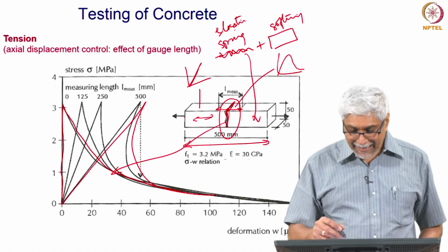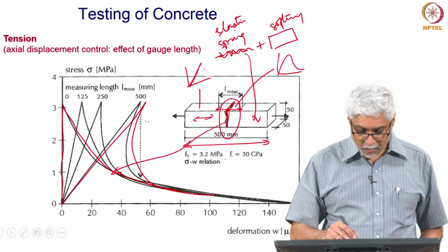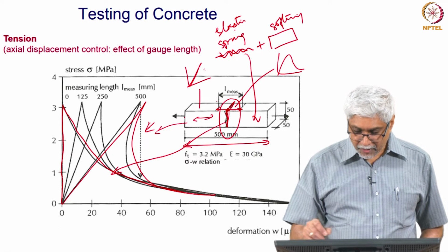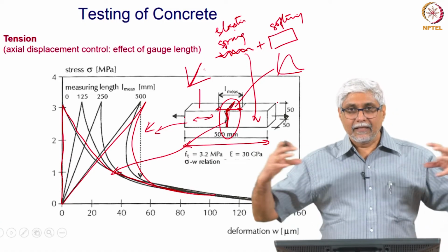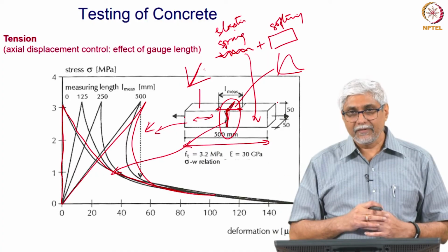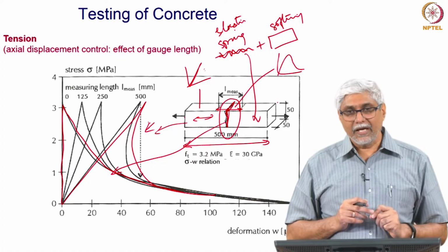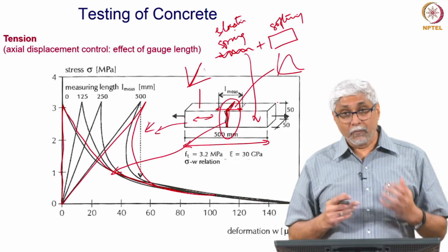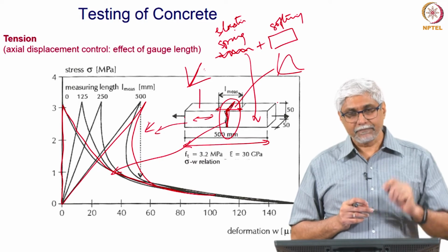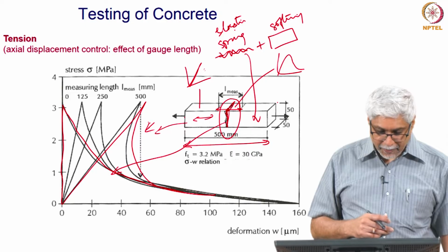Okay. So, when you add, if this dominates you get this type of behavior, when you have a long elastic part, or in the same specimen if you are measuring very far away from the crack and including a lot of elastic part, then you have softening coming in and the test is unstable. So, that is why we have to figure out where we have to put the transducer, and in most tests nowadays we put a notch so that we know where the crack is going to start, and that is where we will put the transducer. So, this is an example again of snapback.